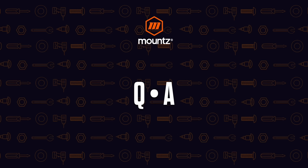Oh, yeah. Thanks, Dave. And then lastly, a follow-up question on the preset tool is, once it's set to a torque value, can it be adjusted to another torque value for a future project? Yes. Each preset tool has a certain range that it can work from. So, for example, if it's, say, 1 to 10 Newton meters, that tool can be set and used anywhere within that range to be set. It can go ahead and be in use.